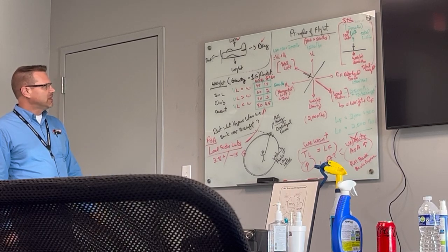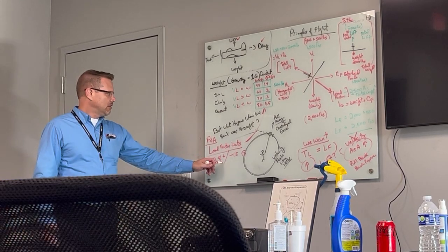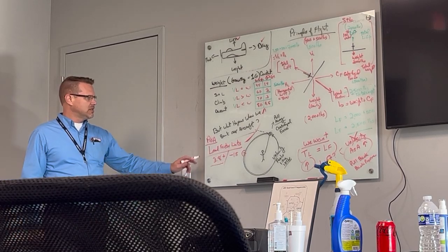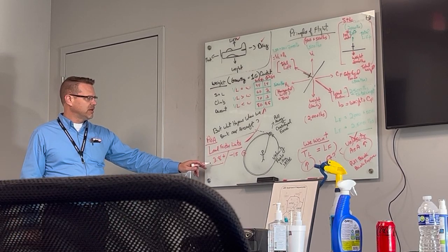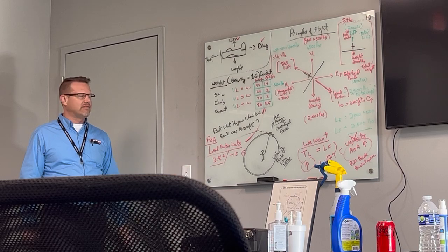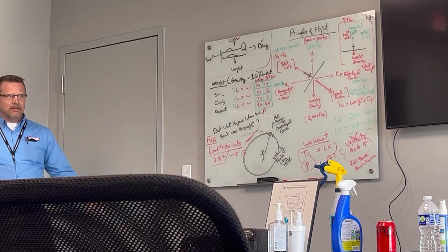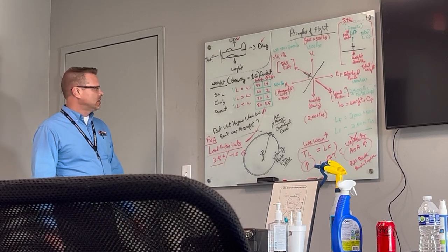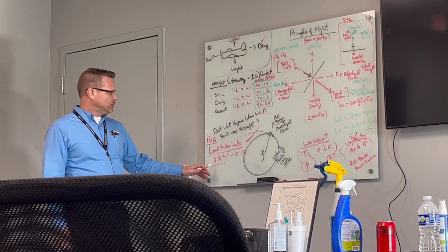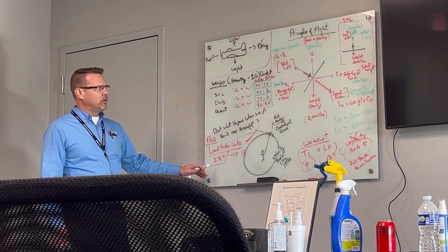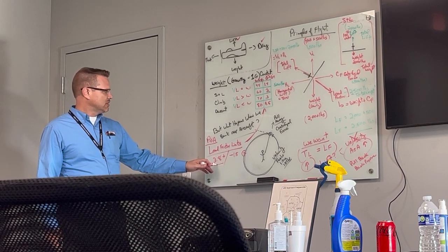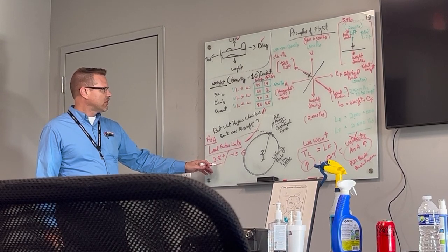Why is this important? Because if we exceed 3.8, what the manufacturer's telling us is the plane is trying to handle 3.8 times the force of gravity, or weight, that we are imposing on these wings. So at some point, the wings can't handle any more stress. And this is the limit that the manufacturer has determined for our aircraft.